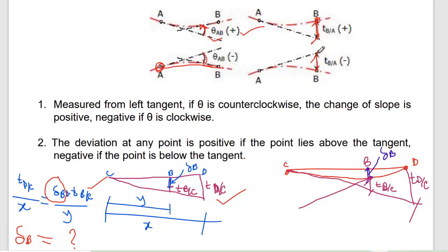So look, this is the tangent and this B point is below the tangent, so that is negative. So based on the tangent location they consider the plus and minus. Okay, so this plus and minus doesn't mean that your deflection is minus or rotation is minus. It means the directions. Keep in mind, distance cannot be minus. Distance minus means what? It's the direction, opposite direction.